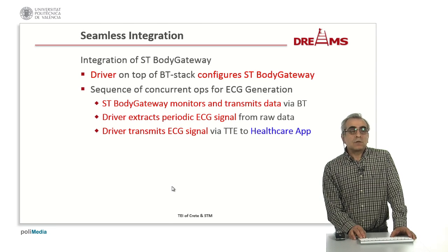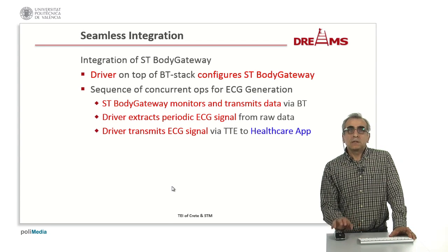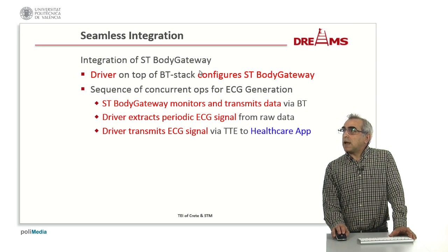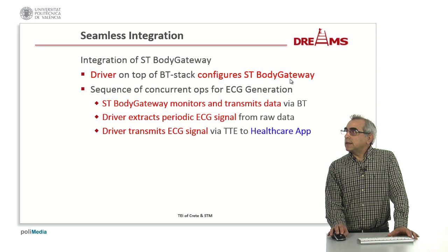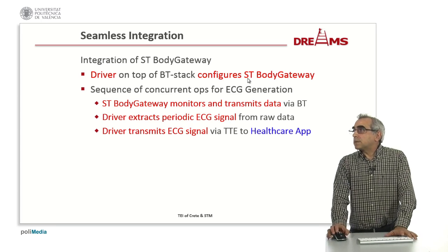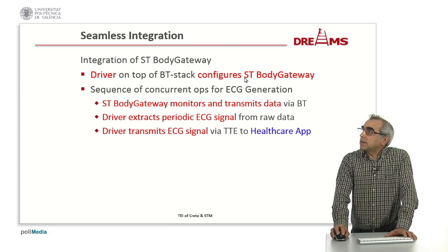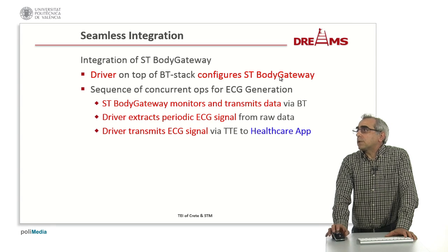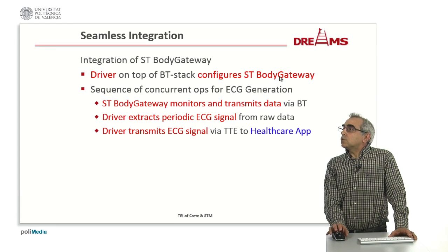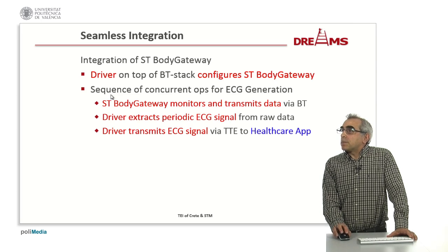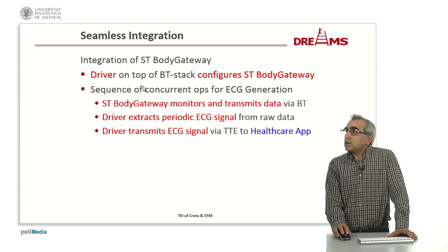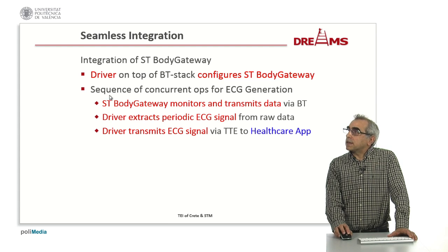The seamless integration of the ST body gateway is very important. Not only do we have the driver which configures the body gateway, sending messages to ask the body gateway to send particular ECG signals, for example, or other particular data in a specific fashion. For example, we use the ST body gateway with 256 samples per second,